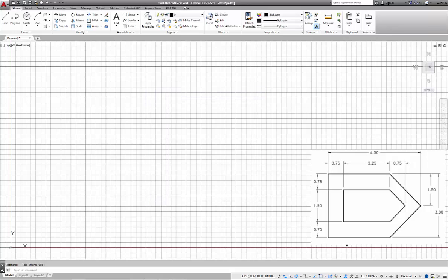If we need an additional tool, we can choose our object snaps again from the drop down. If you look at this little button here next to the object snap box, and 4 doors down is the polar tracking. So we can hit the down arrow right next to our object snap setting and choose tangent if we needed to, or choose nearest for that single click as opposed to having it set full time.